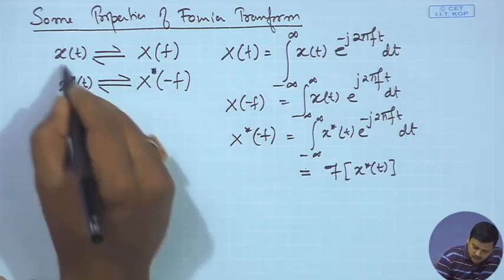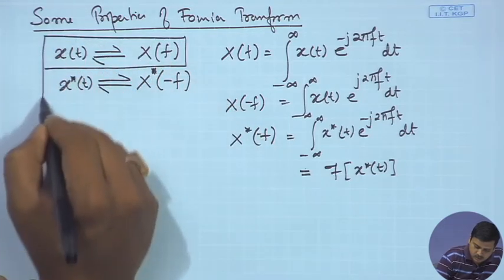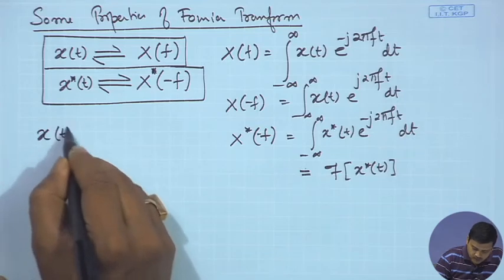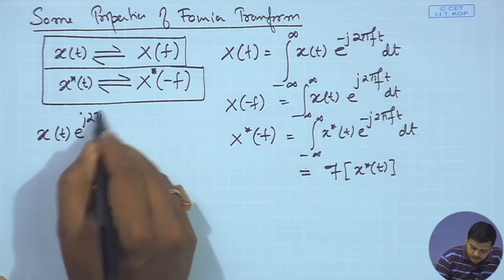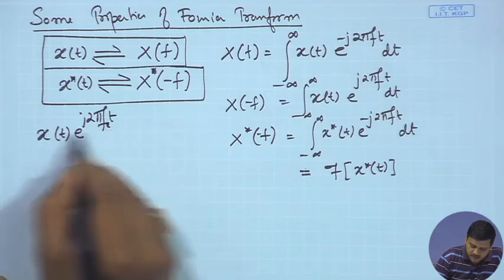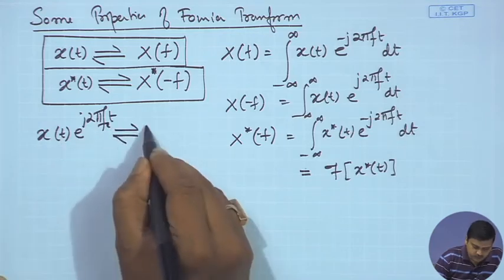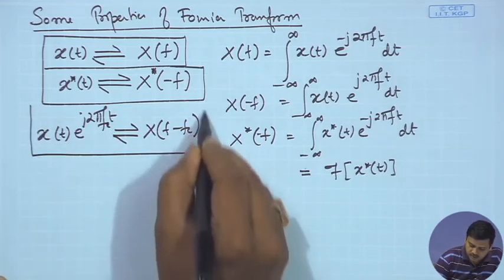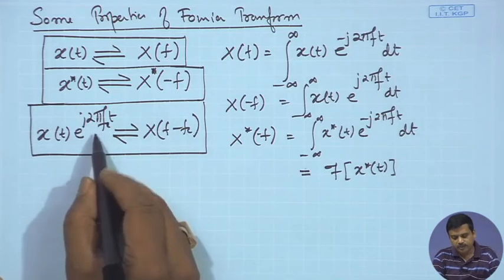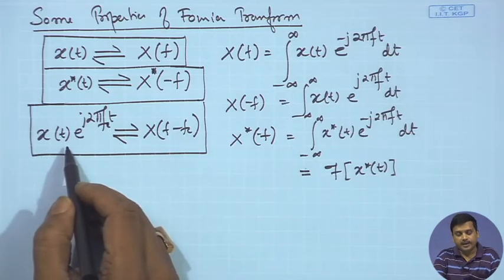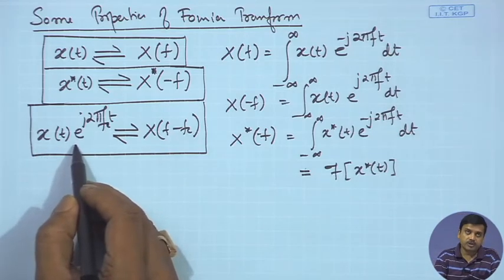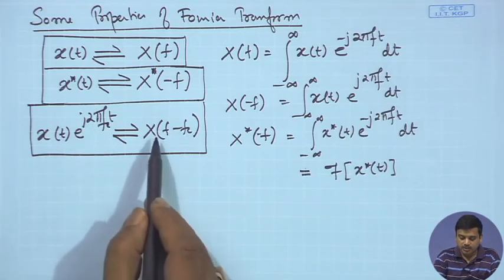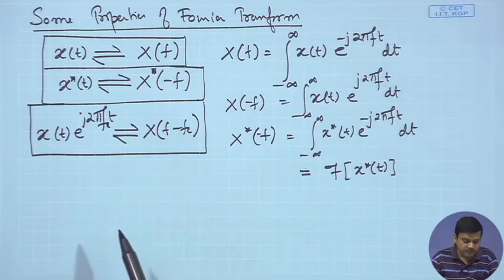And also we will use the shifting property, which is basically the modulation operation, presented as X of f minus f c. This is the shifting property which you have encountered earlier in the modulation process, where there is a signal and you multiply by some cosinusoid. So, the spectrum would appear shifted.